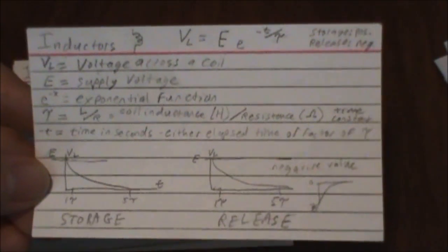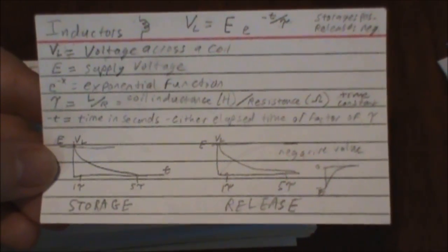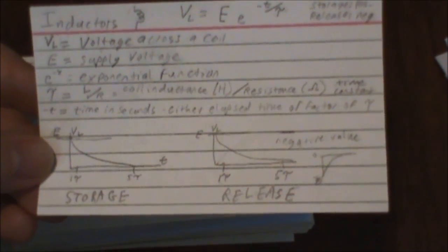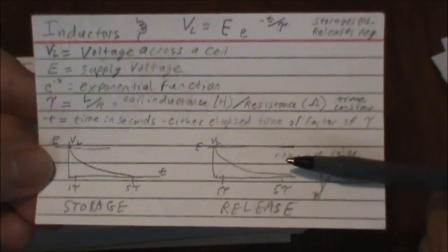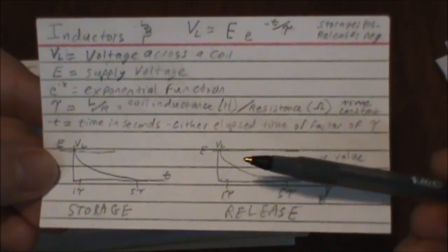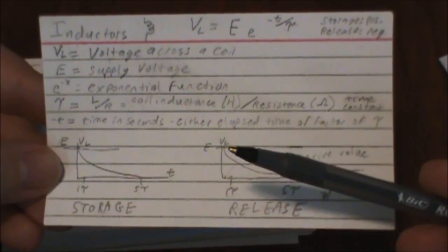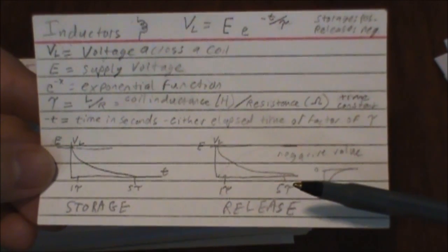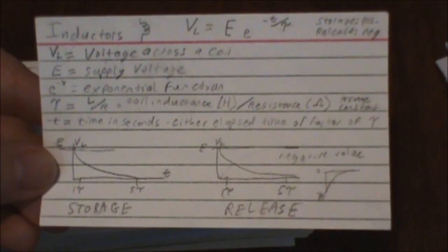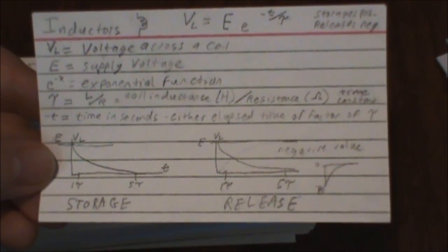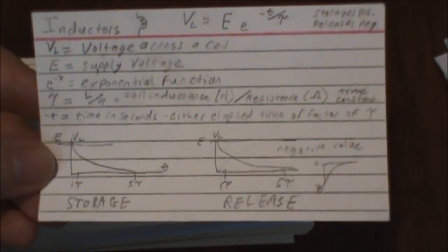But even if we put a battery across an inductor, which is not very common, it still will behave this way in either direct or alternating current. It will briefly have a voltage, and that voltage will disappear, and it will simply act as a conductor, because an inductor is a coil of conducting wire. So after this very brief time, it's going to act like a short.